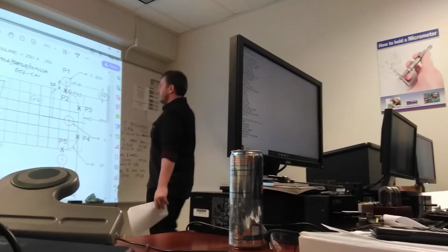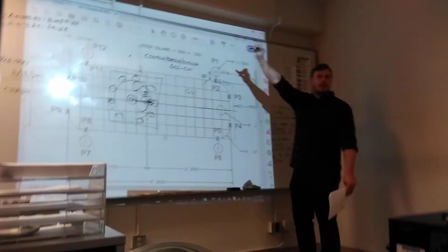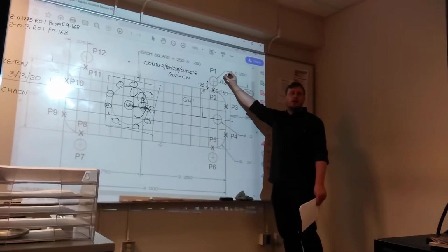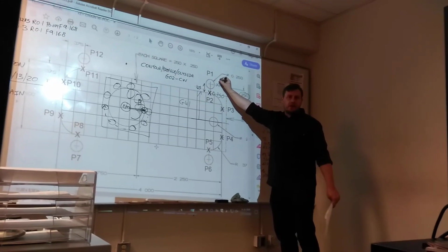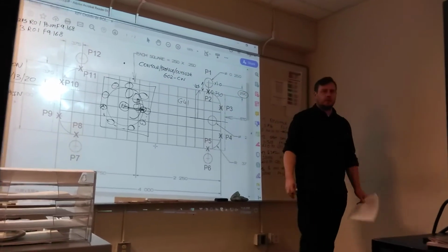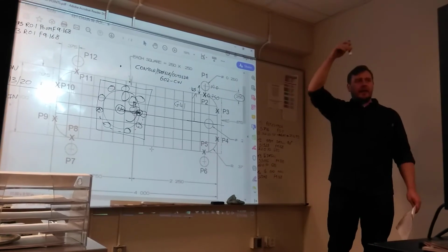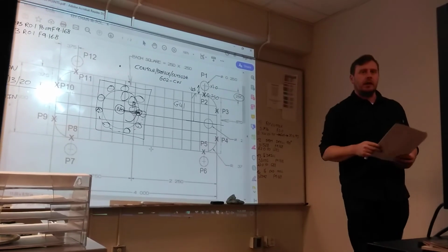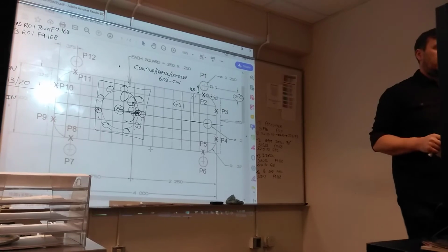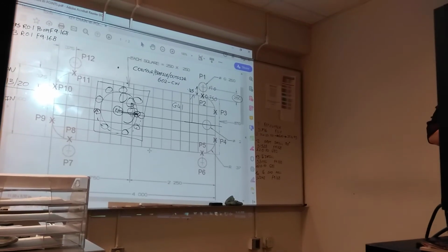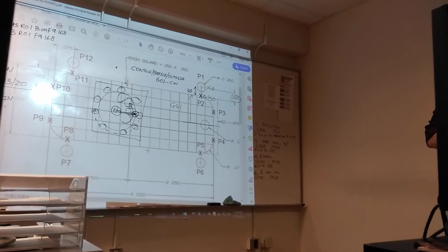So you're going to move to the clearance position. You're going to bring the Z down. Now you can activate cutter compensation. Don't activate it and then bring the Z down. It doesn't work correctly. So always bring the Z down first.